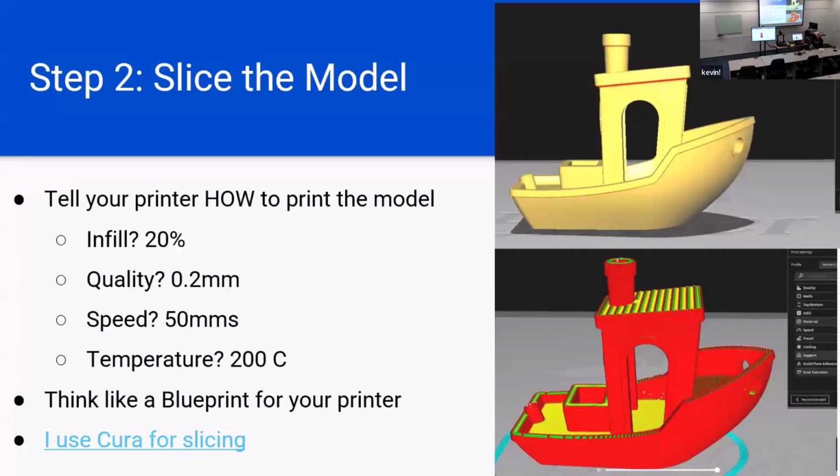There's a lot of configurations that you can do for it. So for example, if I were to shrink this down and cut into the different layers that are in this guy, you can see these little honeycomb sections in the middle of it. This is called the infill. These things are mostly hollow, one, to save material, but two, to also save print time, because otherwise it's going to turn into a very, very long print. Maybe you don't want a 10-hour print or something. You just want a silly little Pikachu or something, right?